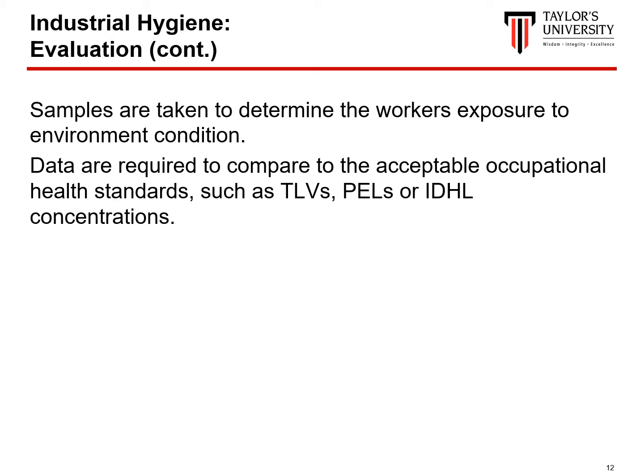After the exposure data are obtained, it is necessary to compare the actual exposure level to the acceptable occupational health standards, such as TLVs, PELs, or IDLH concentrations. These standards, together with the actual concentrations, are used to identify the potential hazards requiring better or more control measures.